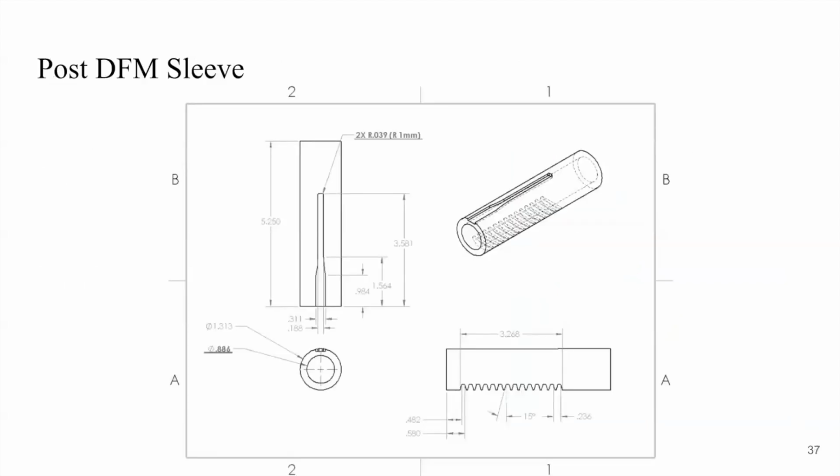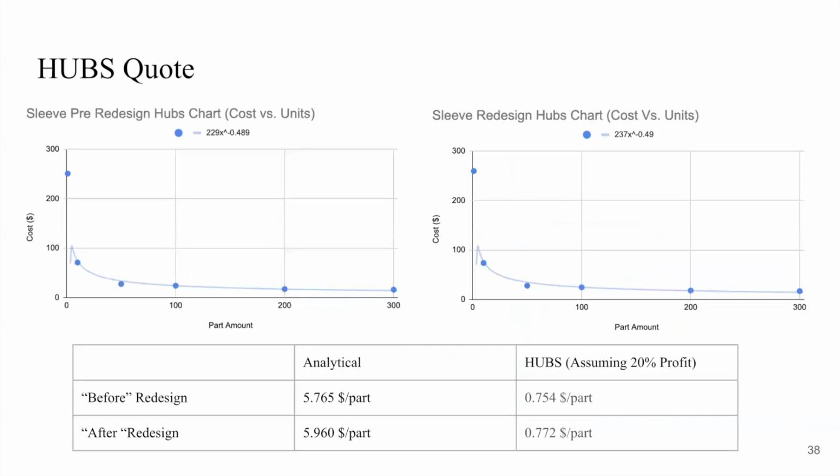The redesigned sleeve has filleted corners, as previously stated, to avoid additional work after milling, allowing for a 2 mm end mill to be used for the entire group. Additionally, as previously stated again, the center through hole is a standard drill size for simplicity. The changed dimensions are shown in bold and underlined.